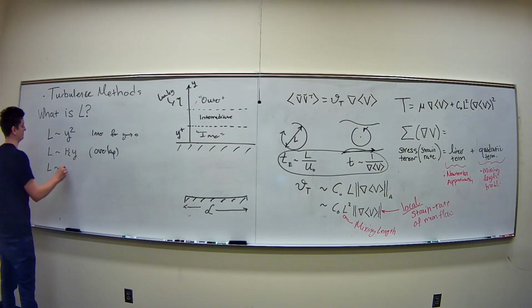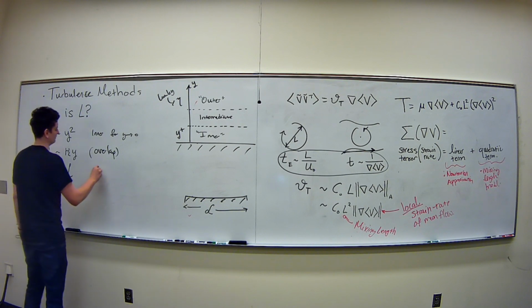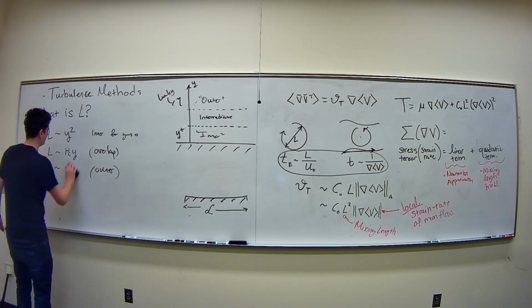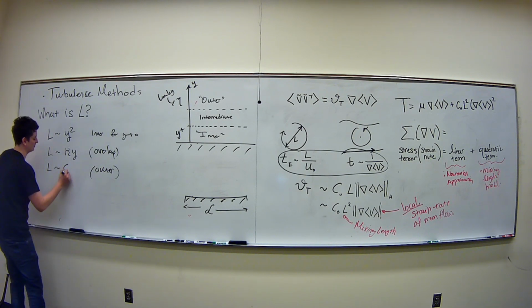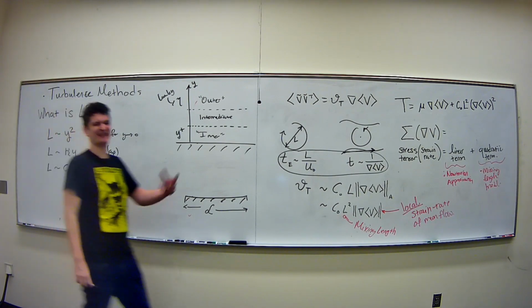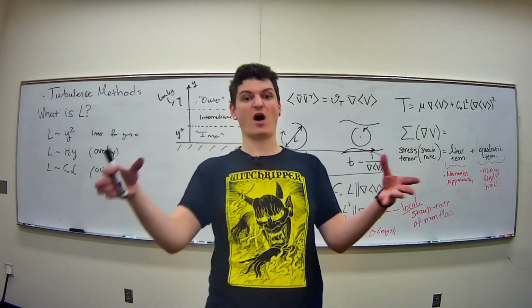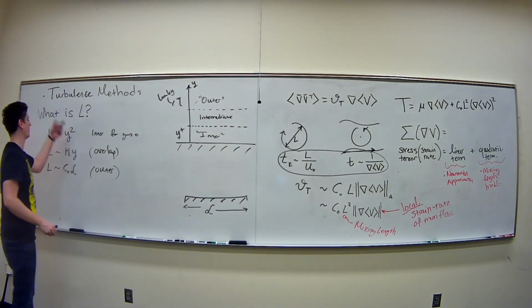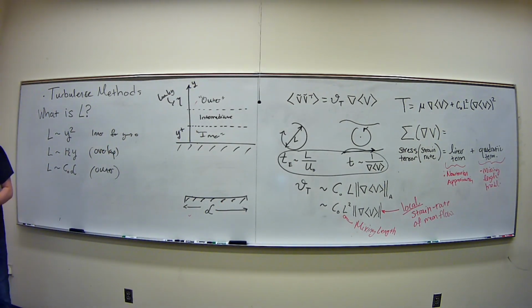And then you have outer. I mean, in reality, there's sort of more of a, let's say, yeah, so then the outer wall is really governed by the length scale of the flow, the length scale of the wall or the flow domain itself, and then some scaling constant as well. But it's constant. There's no y dependence happening in there in your variable.